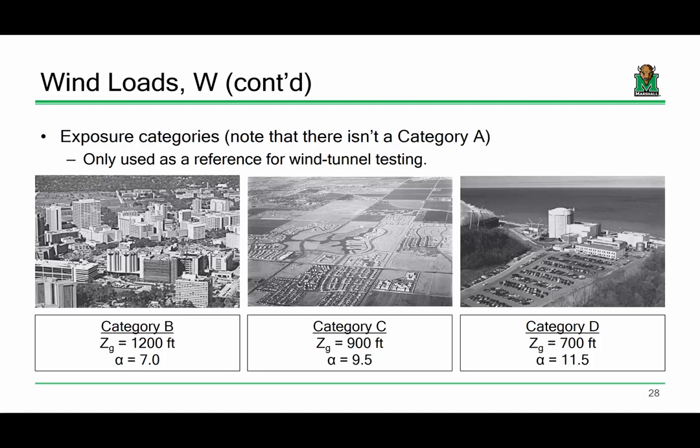For instance, I'm from Bluefield, and there are areas in the Bluefield, West Virginia area that are counted as special wind regions because you're basically in one big valley, so it changes. I'll say this, in this area, like in Huntington, if I was designing a building in Huntington, I would probably go with exposure category C. This isn't Manhattan, but that's me.